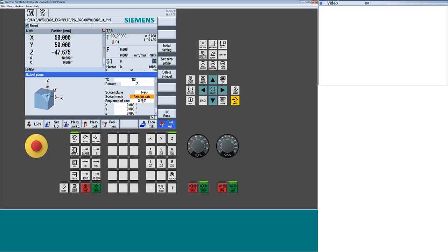Axis by axis, you just tell it, hey, I want to spin 45 degrees around this linear axis of Y. And the system will then say, oh, well, in that case, I got to spin my platter, and I got to spin my table, and it'll figure that out for you. But we're going to do just a simple retract to a set location. So we're going to leave everything at 0. Where do we want to go? The final thing is our direction.